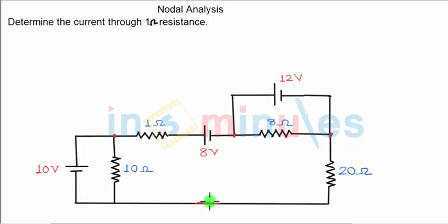And this bottom line is the fourth node, and we always take this bottom node as the ground or the reference node. So we'll continue to do that. With that, I'm left with 3 nodes. Let me define voltages at all the 3 nodes as V1, V2 and V3.